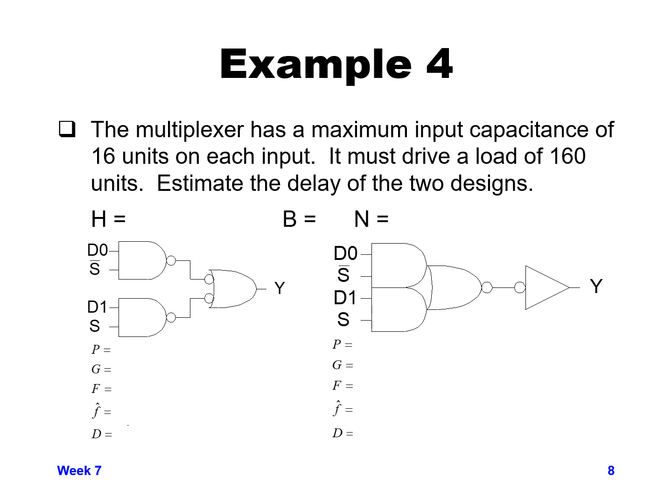The path electrical effort, keep in mind, is based on the capacitance at the output to the capacitance at the input. So in this case, we said we need to drive an output load of 160, and we have 16 units of load at our input, the way we defined this to begin with. So our path electrical effort is a value of 10. For branching, you can see in both designs we don't have any side branches. So our branching for each stage is 1, relatively easy.